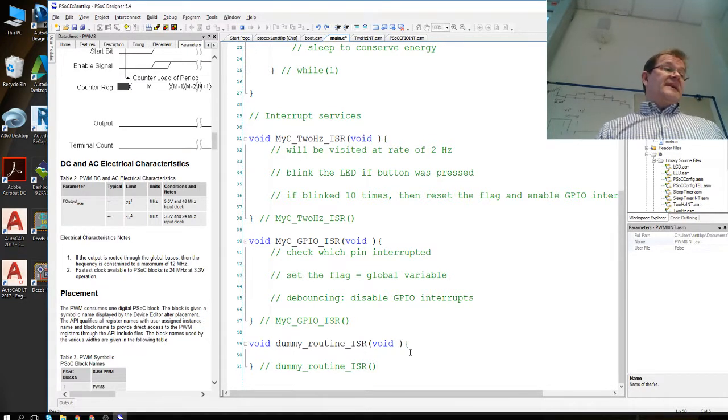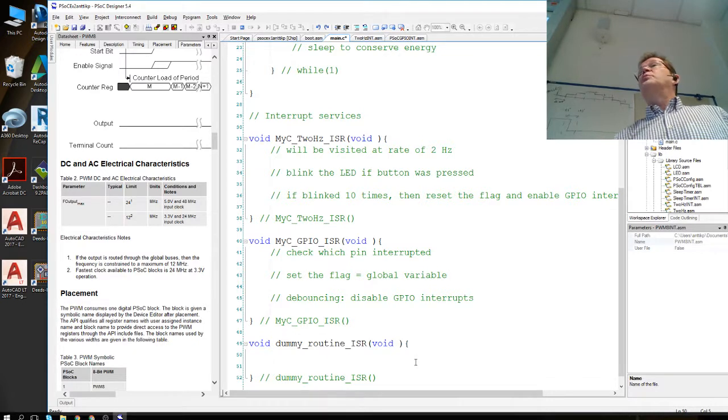Okay, inside of that one, actually, you would use a loop counter because you want to wait for 100 interrupts before you do anything. You can use a global variable, but you can also use static local variables. So static local is basically you can initialize it at 0, and then after that, you can use it and change the value.